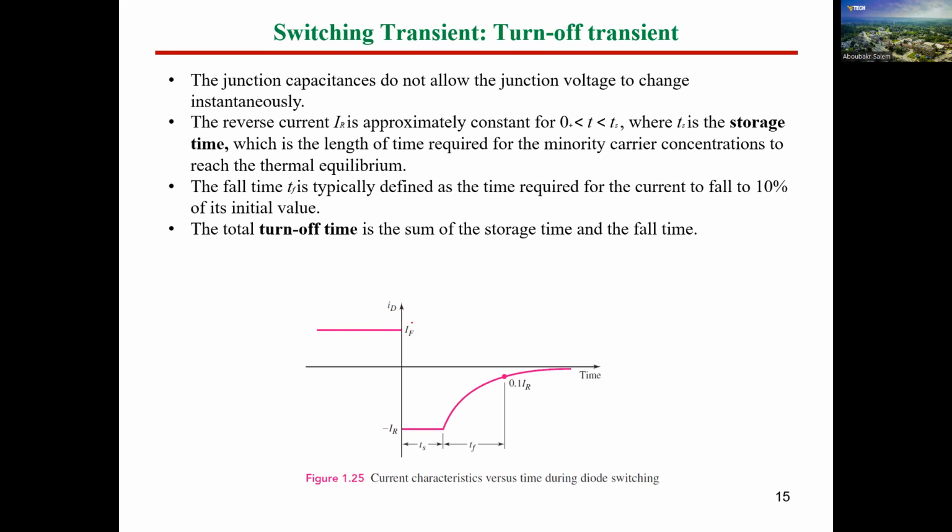So we mentioned that in order to have the diode on, you have to have V diode greater than V barrier. So this is the condition to turn on a diode. But what's the condition to turn off? In order to turn a diode off, we actually have two conditions. Either the voltage should be reversed, but we have another condition that has to be achieved, which is I should reach 0 or less than a value called latching current. So the diode will not be turned off if there is a current flowing in the diode itself, even if the voltage is reversed across this diode. And we will see this later on in our class.